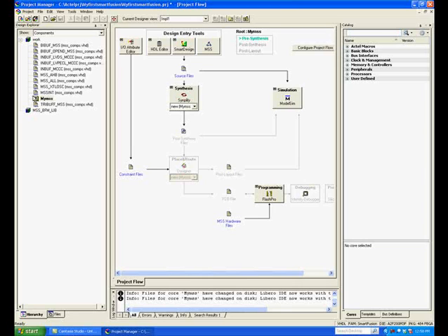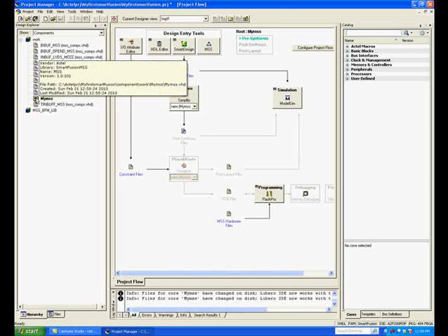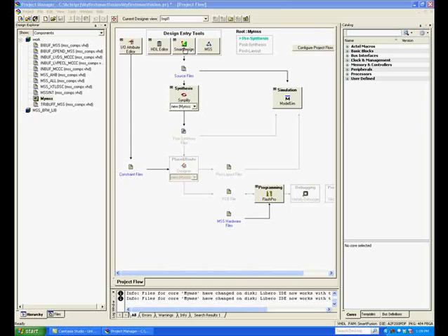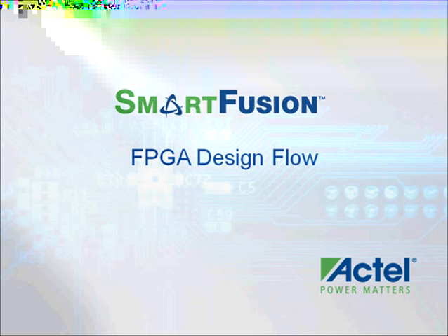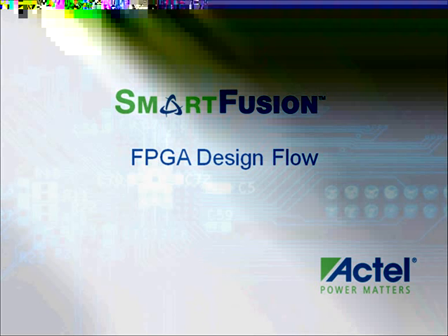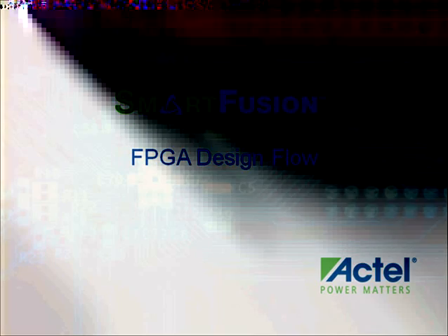To make use of the available SmartFusion Fabric, open the Smart Design by clicking the Smart Design button on the Libero IDE Flow window. Name the Smart Design project My Smart Design and click the OK button. The Smart Design canvas opens.